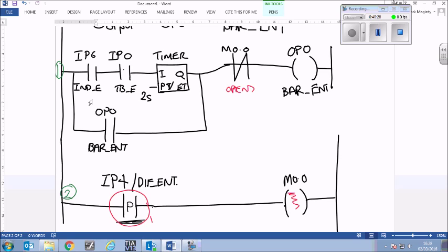But if that's only on for a few milliseconds or whatever, is that enough to let the barrier come the whole way down? Well, yes. So what you're thinking about there is when the barrier's in its up state, and then the car moves forward and activates this positive edge. So the car clears the beam of light, the positive edge activates, M0.0 activates here at the bottom right of the screen, and then this one, what I've written open below currently, it opens.